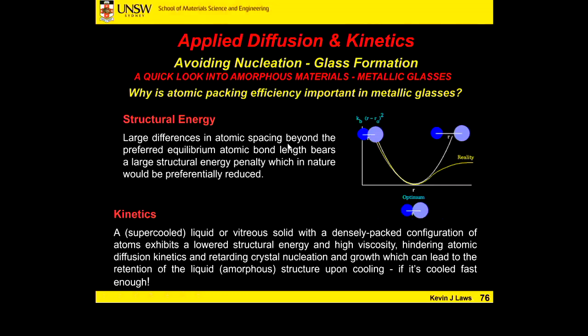If the structural energy of the liquid is very close to that of the solid, the driving force is smaller. You might remember from our first slide, our classic nucleation slide, we had the free energy of our solid and the free energy of our liquid plotted on the same plot. Essentially those 2 lines are very, very close together in these systems. So you have to move a long way or provide a great deal of undercooling to increase the driving force for crystallization in these systems, because of that very low difference in structural energy between the 2.